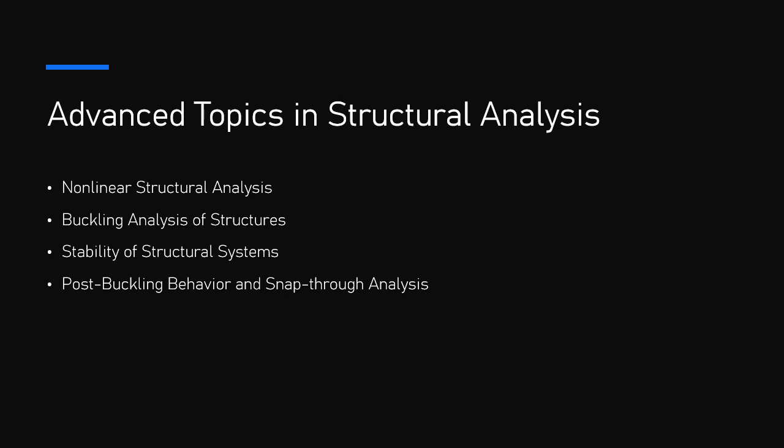10.2. Snap-through instability. Snap-through instability is a type of nonlinear behavior that occurs when a structure experiences a sudden and dramatic change in its configuration. Unlike typical buckling, where deformation is gradual and predictable, snap-through is characterized by a sharp transition between two stable equilibrium states, often caused by a small disturbance.